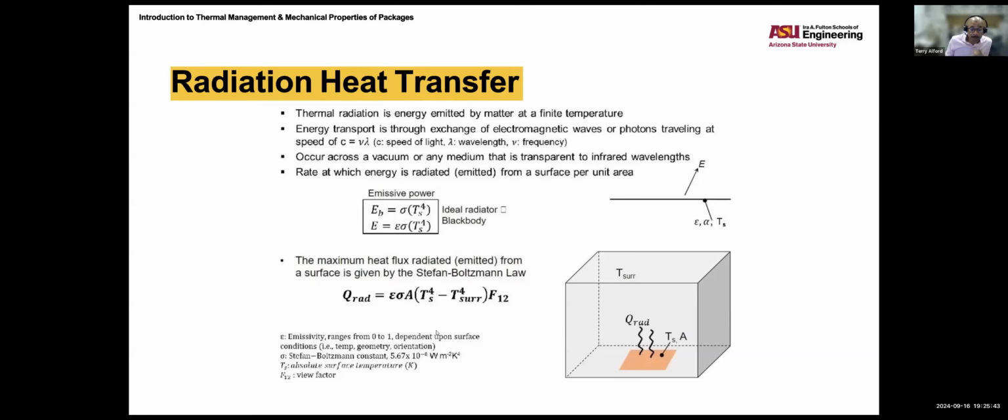For the heat spreader, it's L of the spreader over the thermal conductivity times the area. Likewise for the TIM and the die. In the next level of the course, you would actually have to do these calculations, but we will give these to you if you have these values. So now, since they're in series, we're going to add them up.